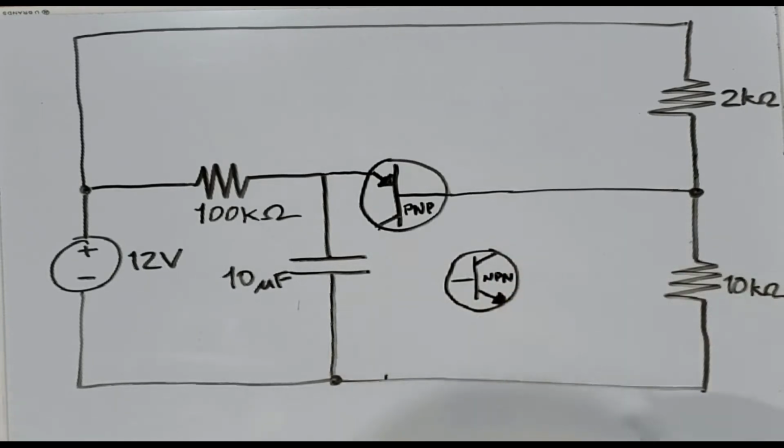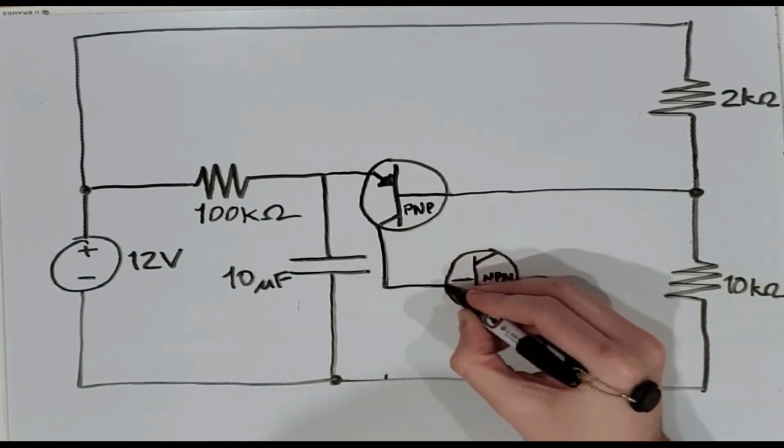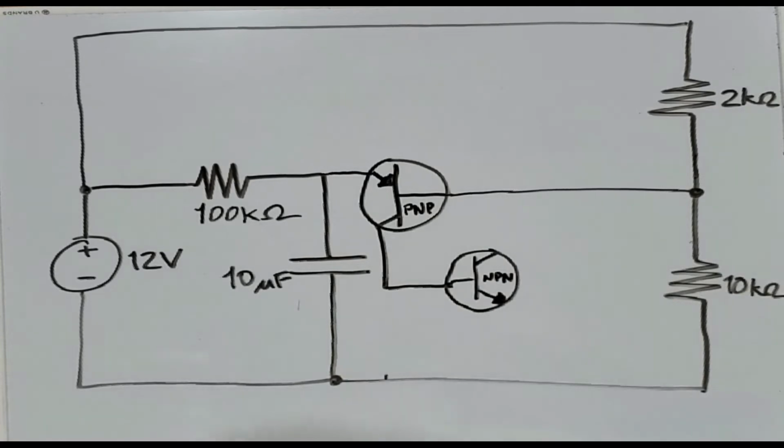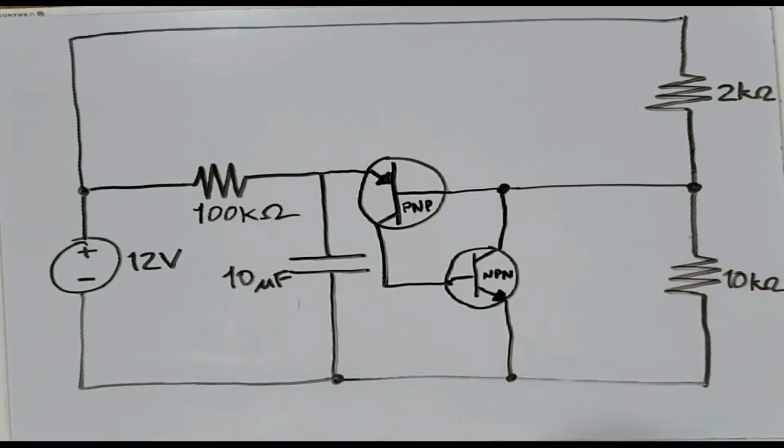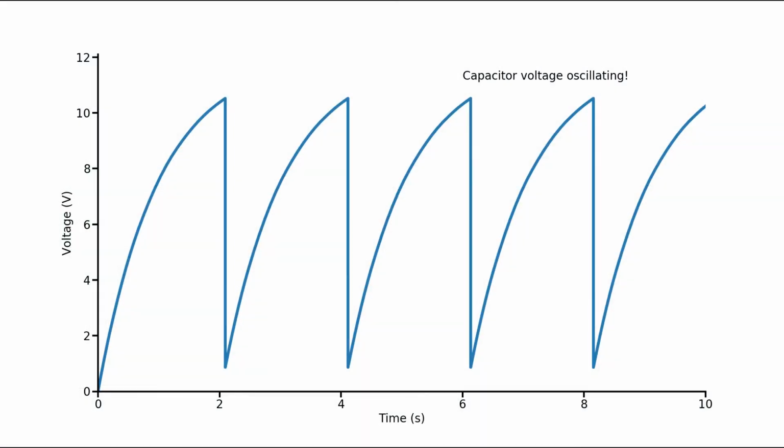So, when the capacitor reaches that appropriate threshold voltage, the PNP transistor saturates. This quickly saturates the NPN transistor, shorting this node and bringing it down from 10 volts to 0-ish volts. And then, once it's at nearly 0 volts, it's low enough that the PNP transistor will stay saturated and let current flow for much longer until the capacitor has discharged practically down to 0.